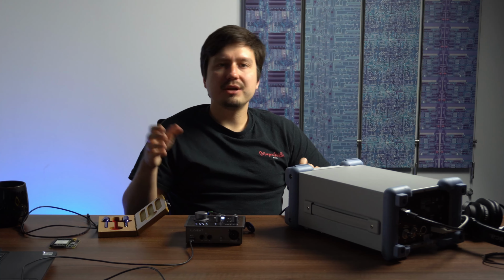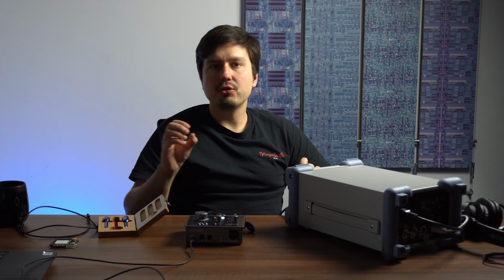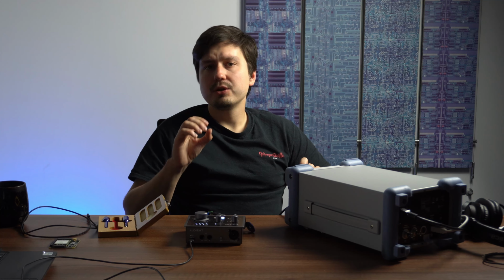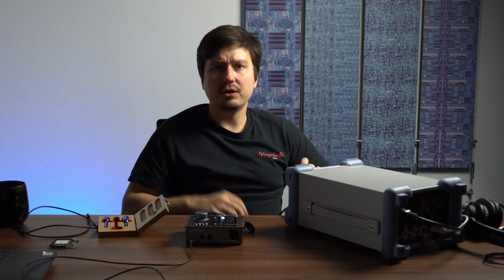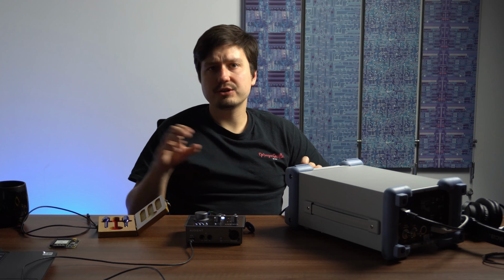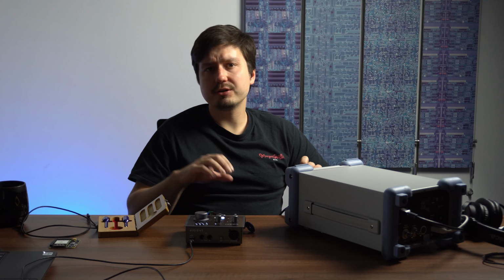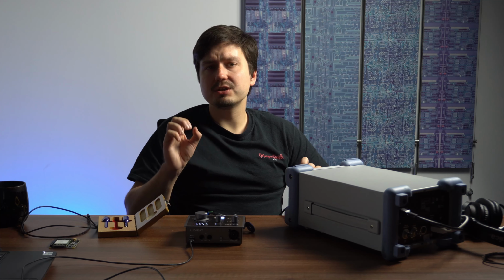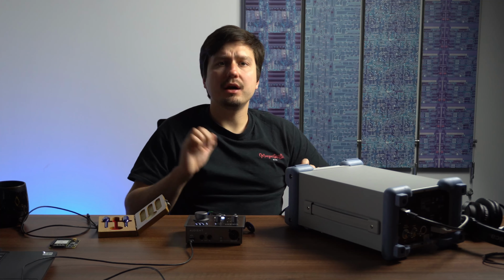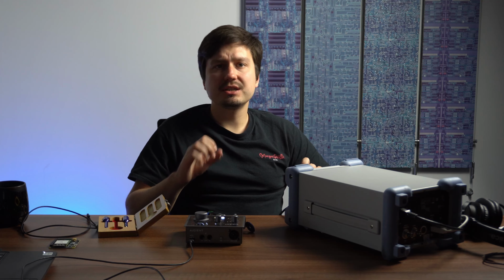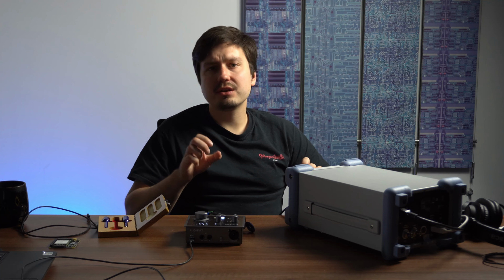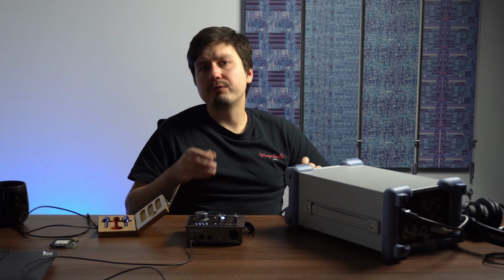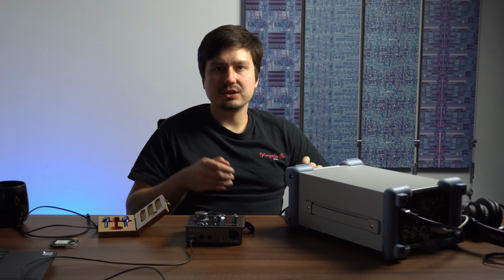This is a very useful feature when you want to measure or find the clock frequency, because if you are seeing multiple rasters, so for example coming off a power supply, like harmonics, then you can see the distance between those spikes, and this distance is typically going to be the center clock frequency of this DC-DC converter.